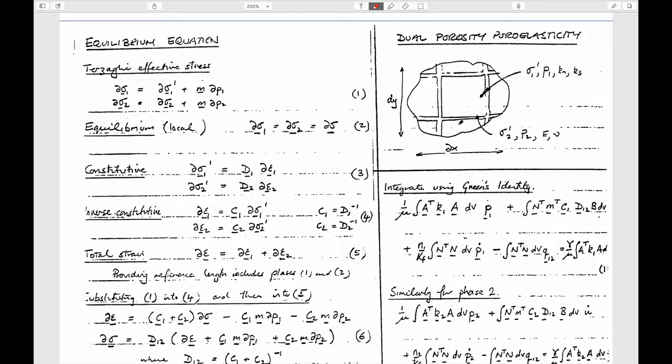So what we could do is define Terzaghi's law of effective stress in terms of the total stress which is applied on the system. Remember, we write the equilibrium equations in terms of total stresses, but deformation and failure is written in terms of effective stresses. And so we need to use this for Hooke's law. So we could write it in terms of an effective stress law for the total stresses in the porous medium, the effective stresses, and the fluid pressures. All of these other relationships will look familiar. And we do exactly the same for the fractured medium as well, where we have the same variables.